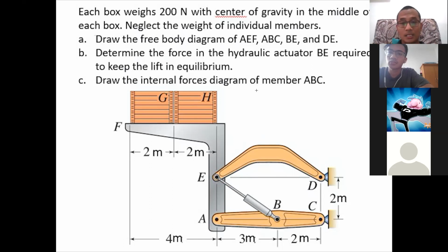direction of the two force member in the hypotenuse of that L. Okay, so this is a frame and machine problem. For this kind of case, what you're supposed to do is first analyze which part is a two force member. If you take a look at the system, ED is actually a two force member, right? If it's a two force member, then the force is supposed to be pointing from E to D or D to E, right? Then beside ED, EB is a two force member as well. So those two, you can treat as two force members.